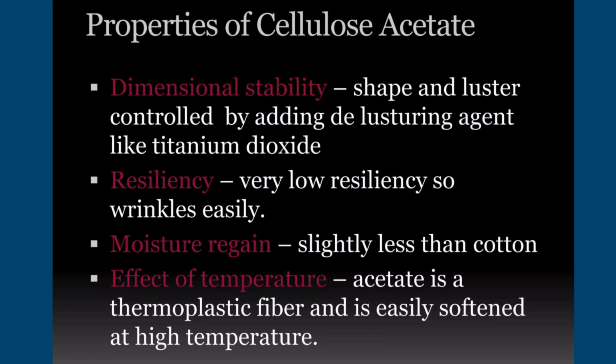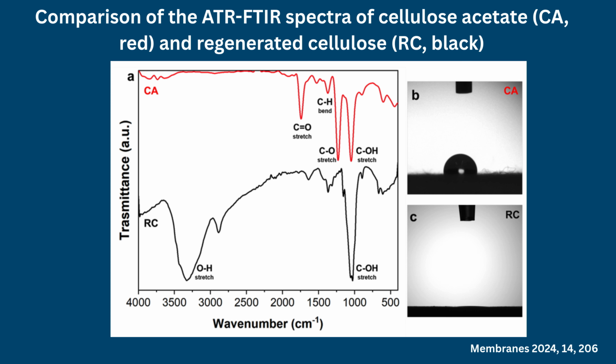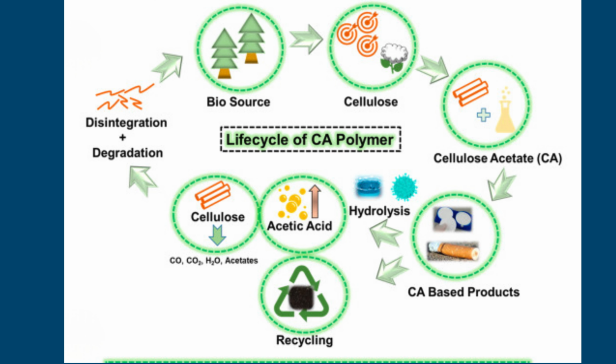Cellulose acetate exhibits an attractive combination of optical, mechanical, and chemical properties. It possesses excellent transparency, high gloss, moderate tensile strength, low density, and outstanding dimensional stability. The polymer absorbs less moisture than regenerated cellulose fibers, while maintaining pleasant softness and silk-like aesthetics. Its reduced crystallinity improves processability compared with cellulose, enabling extrusion, thermoforming, solvent casting, electrospinning, and injection molding.